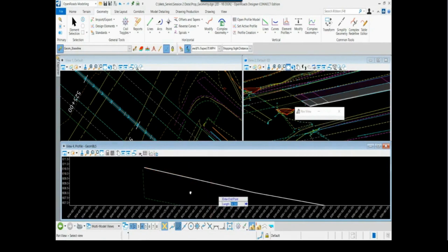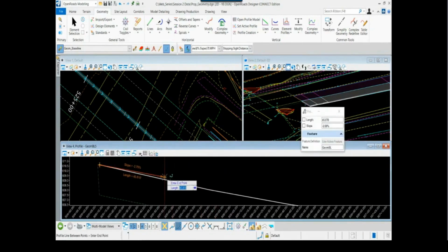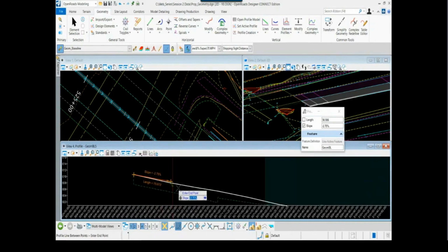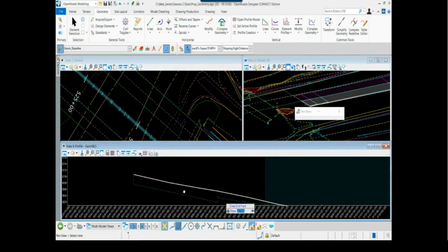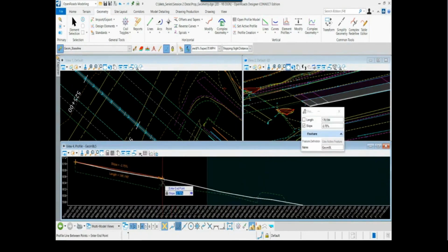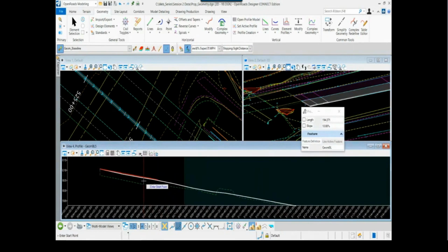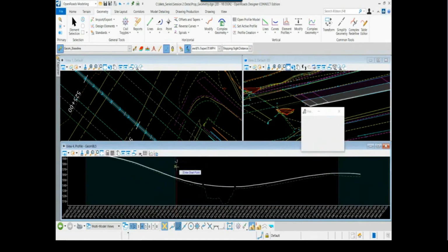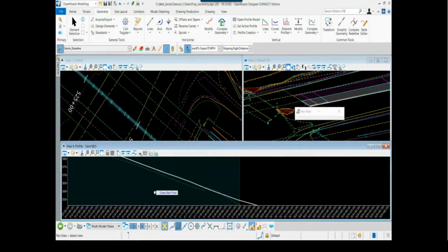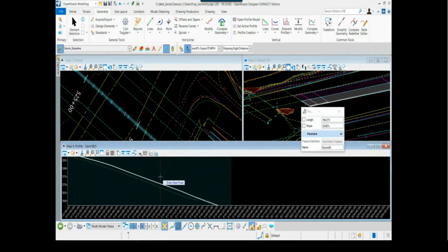Now, as we're laying out this element, I'm going to place tangents, and then fit arcs between them in this workflow. So this first element, we can draw this out. I'm going to hold to a 2.75 grade. So I'll key that value in, and you can see that value. I can actually zoom out. You can see that it fits a little better than maybe it appears. And then draw that segment in. So I have a tangential segment along that edge of pavement. It's that proposed widened edge of pavement using the existing cross slope of the road.